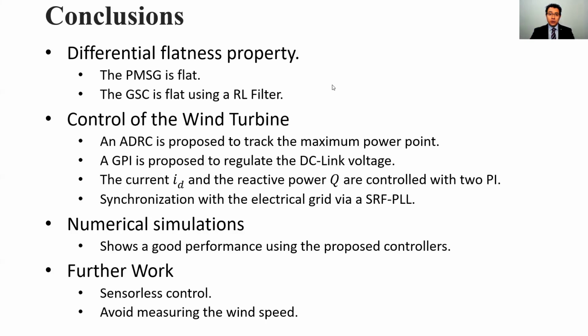Finally, as further work, we aim to design a sensorless controller, namely avoiding measuring the PMSG angular position to track the maximum power curve, and even more, avoiding measuring wind speed.